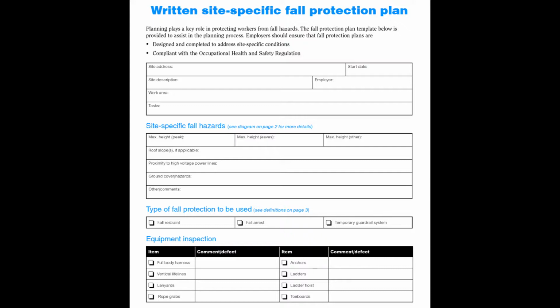The fall protection plan shall include a written discussion of other measures that will be taken to reduce or eliminate the fall hazards for workers who cannot be provided with protection from the conventional fall protection systems. For example, the employer shall discuss the extent to which scaffolds, ladders, or vehicle-mounted work platforms can be used to provide a safer work surface and thereby reduce the hazard of falling. The fall protection plan shall identify each location where conventional fall protection methods cannot be used. These locations shall then be classified as controlled access zones.